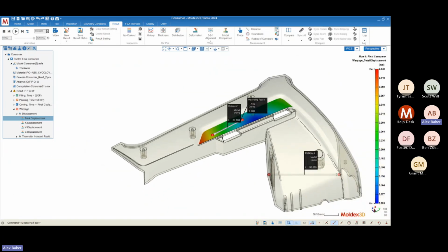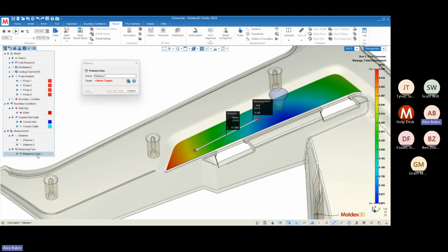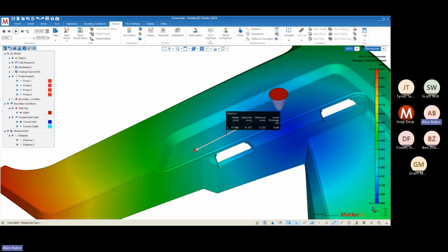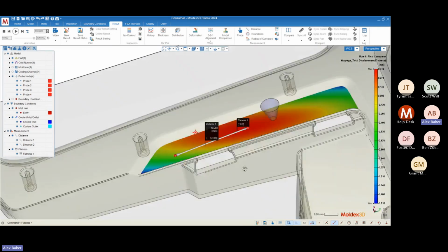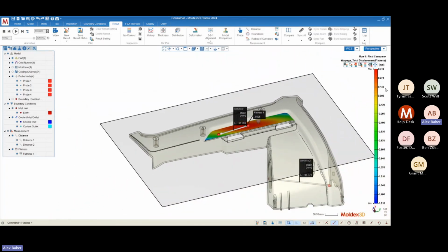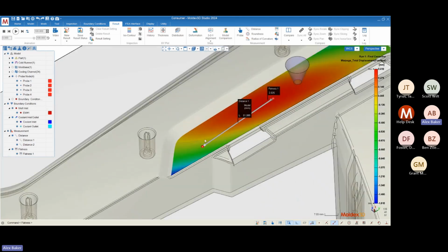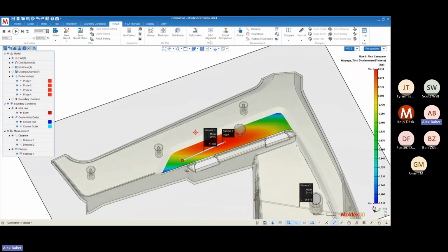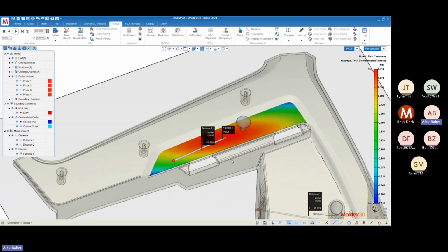We also have a flatness tool. You might have already seen it. There is a flatness tool that does a similar thing. It just creates a flatness plane and measures the deviation. And you'll see a pretty similar color distribution from those. Quick flatness. You can see a pretty similar color distribution. It's inversed because of the fact that it's more of a deviation from the flatness plane. The colors themselves look pretty different, but the actual contour or the actual information you're getting from these two is similar.